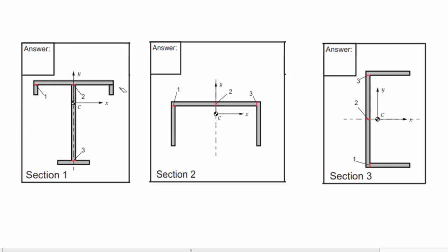We know that in the open ends the shear stress will be 0. So in this end, this end, this end, and this end, there will be no shear stress. From these points inward, the shear stress will only increase. So along this path the shear stress will increase, same with this path, and same with these 2 paths.